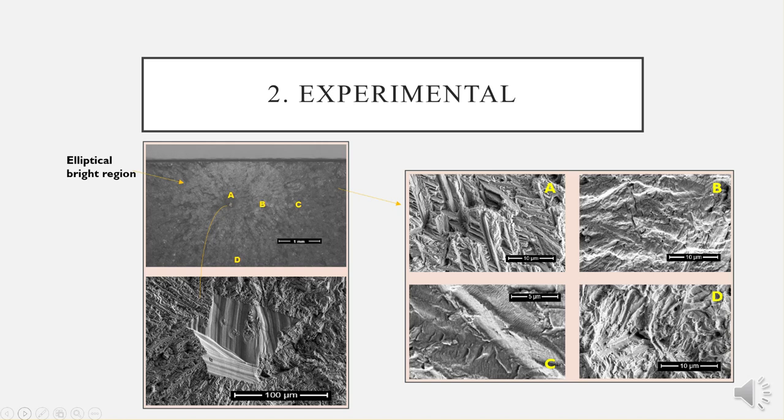It is important to note that no drastic transition is observed, but rather a very slow increase in the amount of striations observed. Last, we find the final fracture region, where a typical dimpled surface can be observed in figure D.